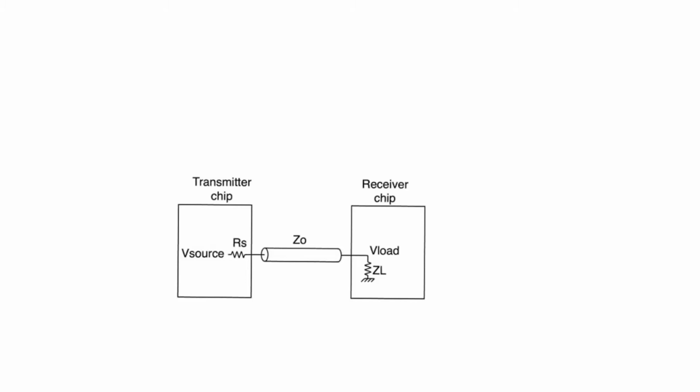And in transmission lines, delay is more controlled, or more dominated, by the time of flight of the signal, meaning the time it takes the electromagnetic wave to actually travel through the length of the wire, rather than by gate delay, which is calculated as an RC delay. So, for example, let's consider the situation where we have a wire with a length of 20 centimeters. This is not huge. I mean, it's kind of long, but it's possible on a PCB.